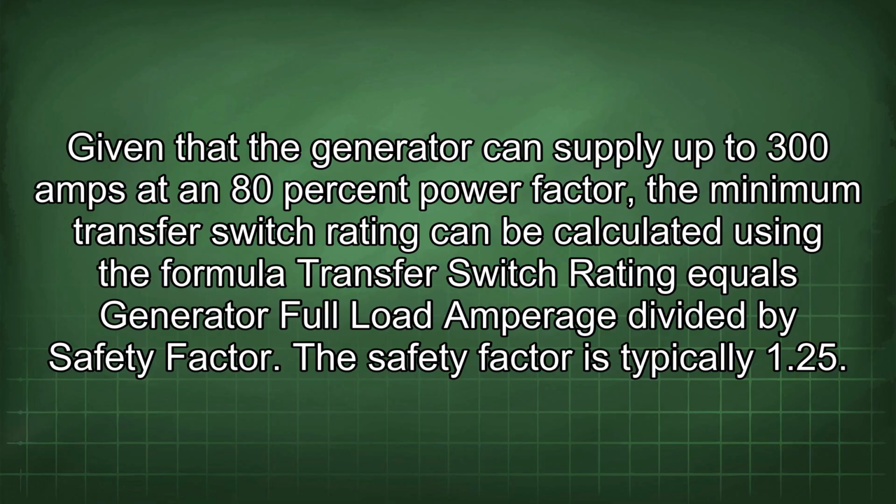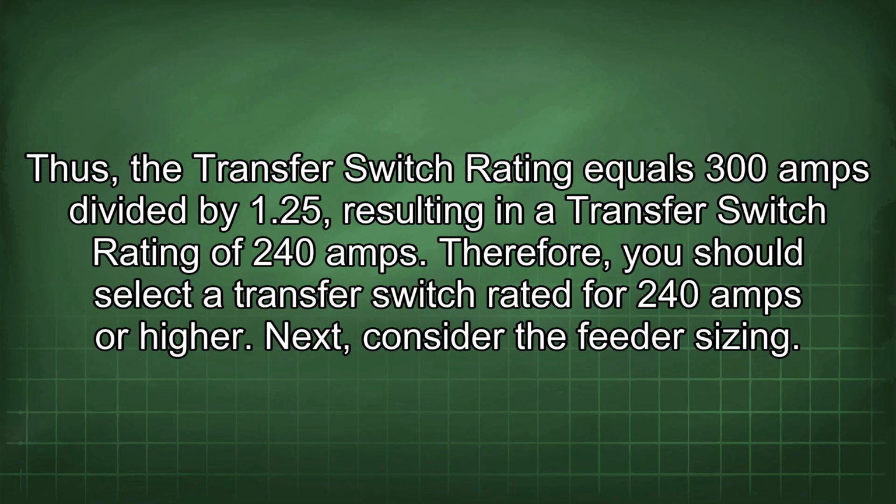The safety factor is typically 1.25. Thus, the transfer switch rating equals 300 amps divided by 1.25, resulting in a transfer switch rating of 240 amps. Therefore, you should select a transfer switch rated for 240 amps or higher.